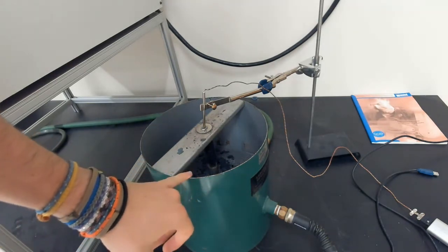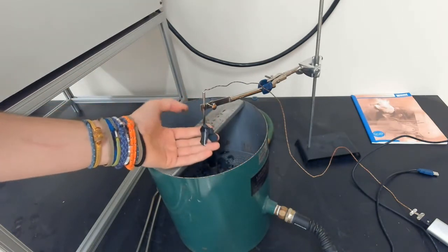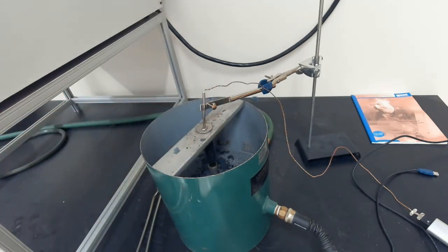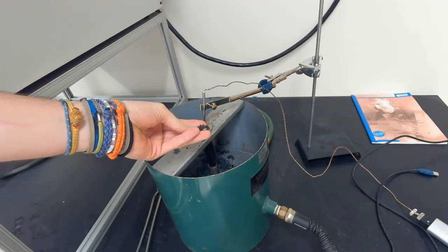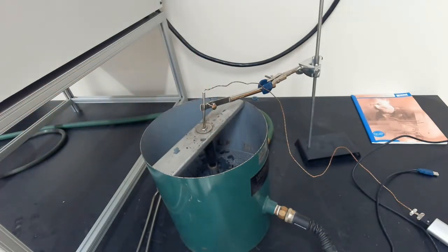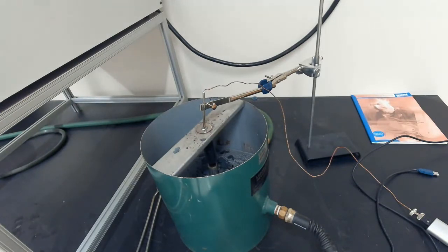And then what you'll see is these flakes starting to form on the outside of the specimen, and some of those will flake off. What that is, is just carbon. This is basically just graphite. As the carbon is forced out of the crystal lattice of the steel and then cools, the carbon forms this graphite, which flakes off. And this is a thermocouple, which is going out to the computer and logging the cooling of our specimen.